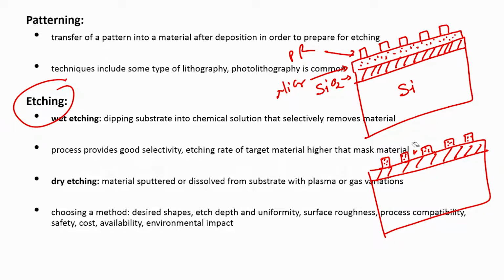Okay. So, how can I protect this nichrome? By using my photoresist. How can I pattern my photoresist in this fashion? Using photolithography. Alright. So, using photolithography we can pattern the photoresist, and this photoresist will act as a mask against the chemical that is used to etch the metal, or a material, below it. In this case it is nichrome, right. Wherever the photoresist was there, you can see that nichrome is still present, is it not.